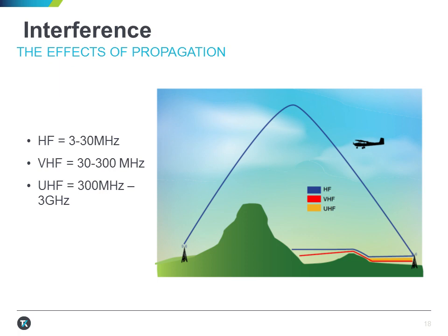In general, VHF communications are line of sight, or line of sight plus 30%, which we call the radio horizon. UHF, however, has a much shorter propagation characteristic. The rule of thumb that we typically apply is that each time we double our frequency range, we halve our propagation distance.